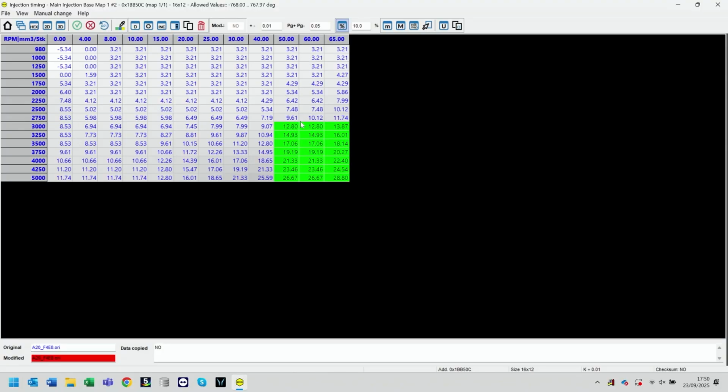where we're looking at our maximum output, the maximum power and performance, and we're looking from an RPM point, not going as low as the 1500 RPM where we raised our torque limit, because again, if we put too much load down in the ECU, in the engine, we're potentially risking overloading it. We typically start timing changes from around about 2000 RPM.